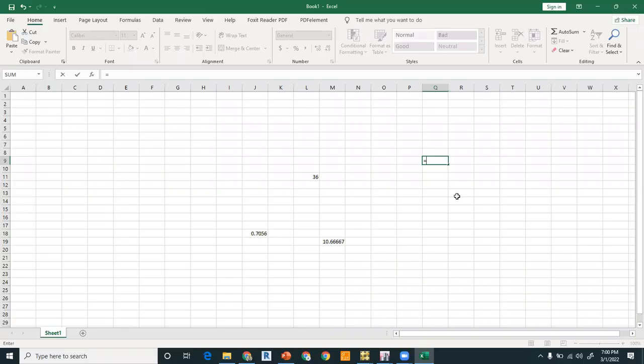At first, in the first layer, you used number 4 bar and we have divided with number 6, so it will be divided 0.5. So 0.88 inch square per foot reinforcement you have provided in layer 1. In layer 2 you have provided again, this is the bar dia and this is the spacing 0.5.